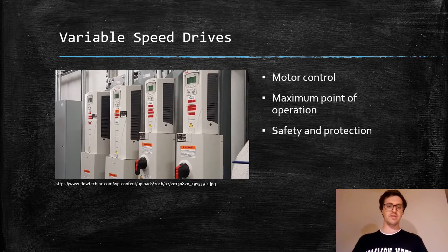The drives are adept at finding and correcting faults without interrupting operations. They can detect events such as pulleys losing traction or motors overloading. Left untreated, these events can cause damage to the equipment, so the VSD triggers a response to prevent damage before it occurs. The drive's control of torque, speed, and acceleration can avoid shock loading.